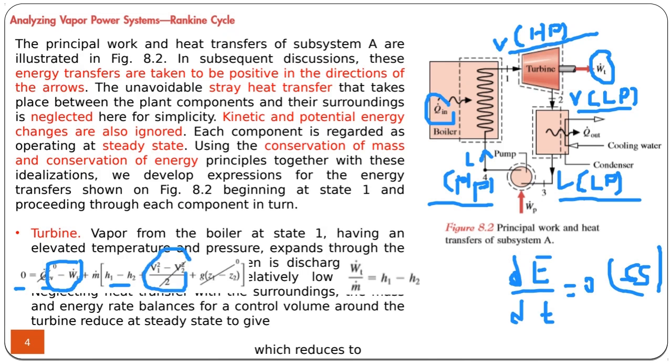For many kinds of steam power cycles, we assume that the change in the kinetic energy and the change in the potential energy are negligible, so that the turbine work per unit mass is just the difference of the enthalpies entering the turbine and exiting the turbine.